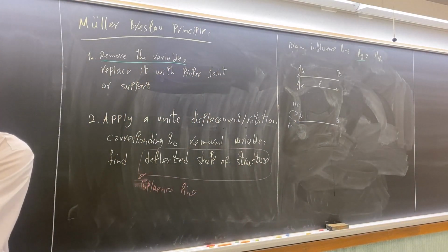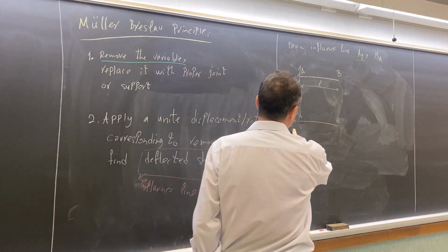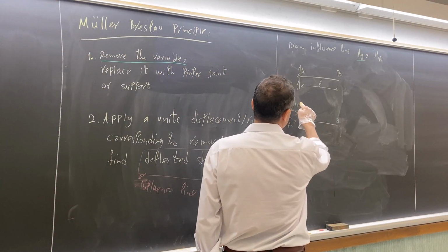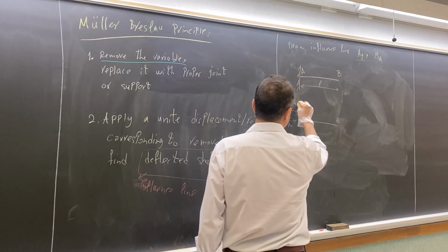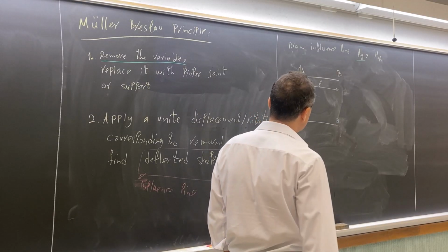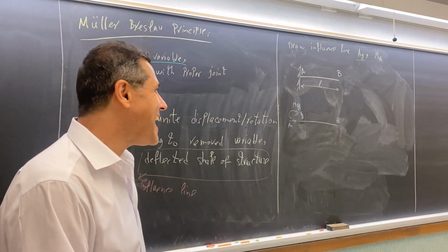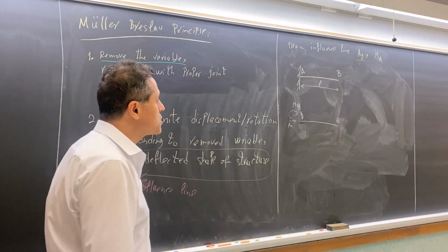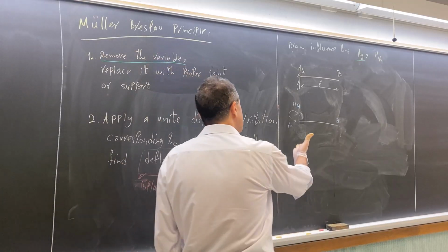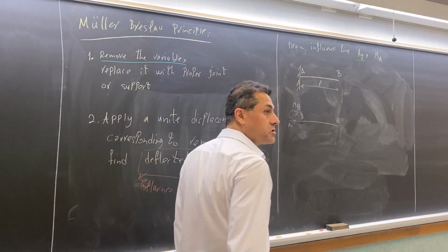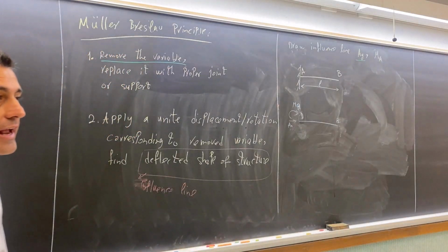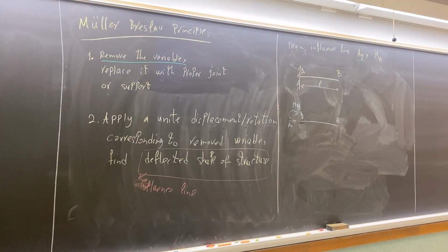The reason is because now you have AX and you have M at point A. So you have to replace it with a proper support. What is that support which carries the horizontal reaction and moment but doesn't carry any vertical reaction? I think Kelemen knows the answer.